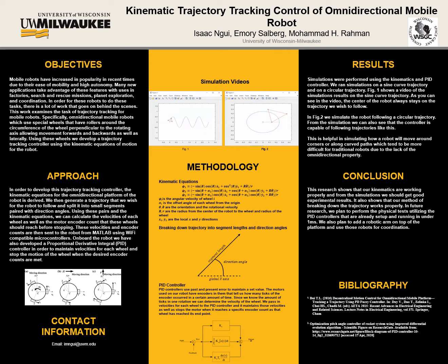So we perform simulations using the kinematics and the PID controller. The first simulation we ran was on a sine wave controller trajectory. And so this video right here is showing the sine wave controller, and as you can see, it shows that our robot stayed on the trajectory very well, and it always kept one wheel on the path that we were trying to follow, which is exactly what we were looking for, and it worked out exactly how we wanted it to be.